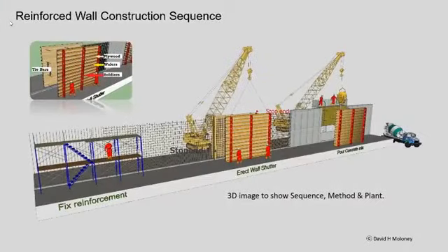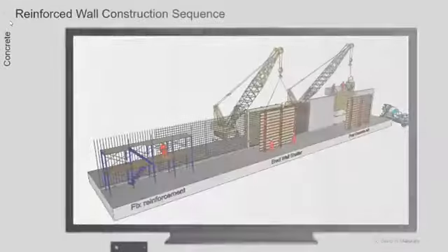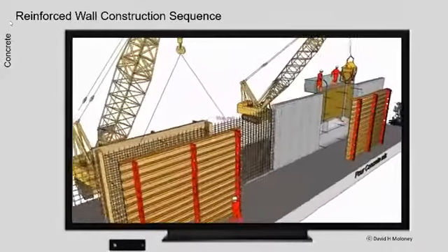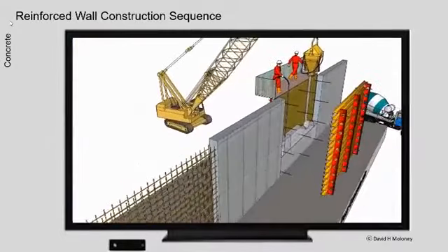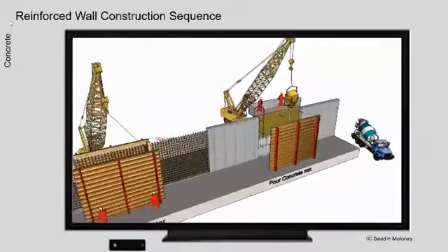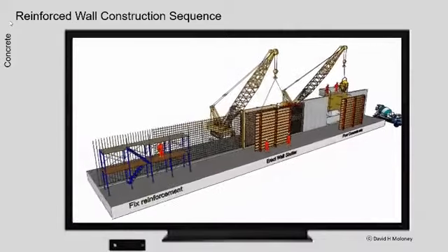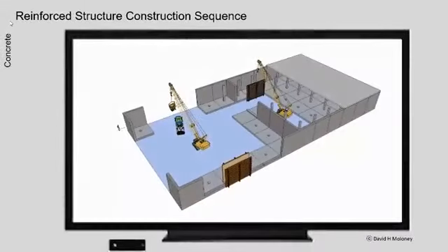Concrete, rebar and shuttering. Concrete wall construction. The sequence to construct a reinforced concrete wall is as follows. Tie the reinforcement. Erect stop ends in the wall shutters. Pour and vibrate the concrete mix. Remove the shutters after the concrete has hardened.